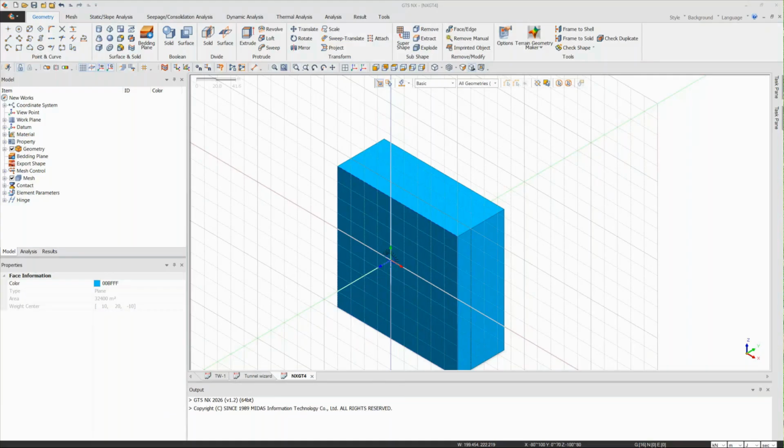For that, you may have to refer to some guidelines for the field monitoring data, as I showed in the case studies where they were comparing the software results with the field monitoring data. In that way the results can also be validated, and we can check whether those settlements, even from the field monitoring data, are allowable or not. So we need to follow some established guideline to confirm that.